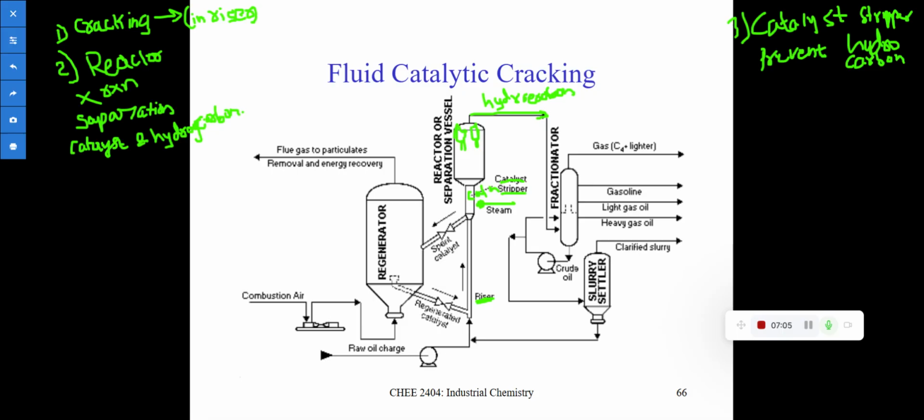Because of this prevention of hydrocarbons, the pressure here should be accurate, because if the pressure is imbalanced in this spent catalyst section, air could go through. Then hydrocarbons could go this way, and air could react in the riser, and this could cause a dangerous reaction. This could burn the entire factory, because hydrocarbons are reacting with the air, and it will burn the hydrocarbons.